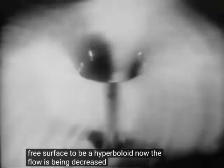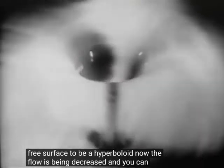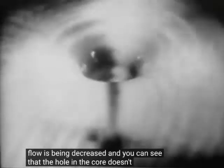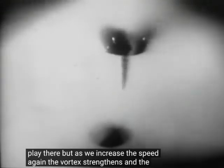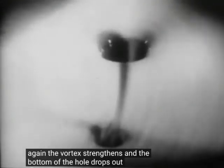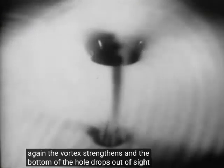Now the flow is being decreased, and you can see that the hole in the core doesn't really extend downward indefinitely. The infinite velocities and shear rates theoretically at the axis are undone by large viscous forces which come into play there. But as we increase the speed again, the vortex strengthens, and the bottom of the hole drops out of sight.